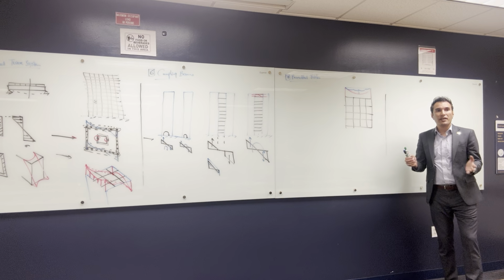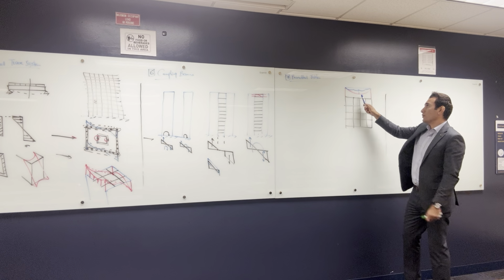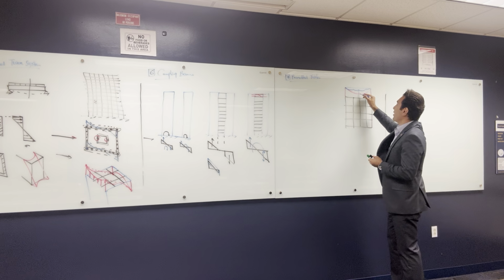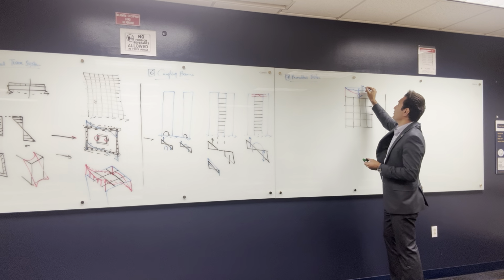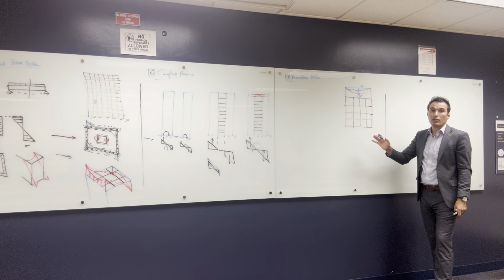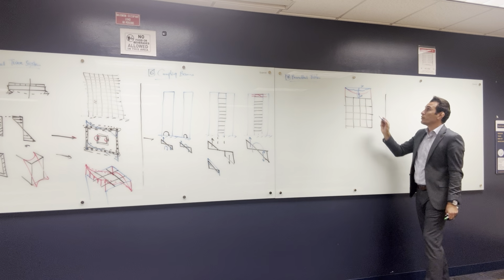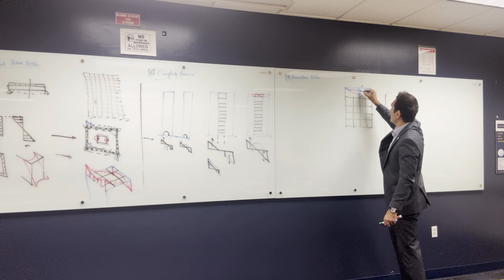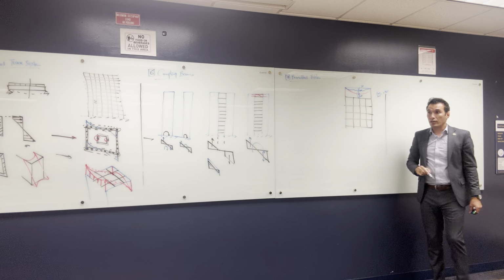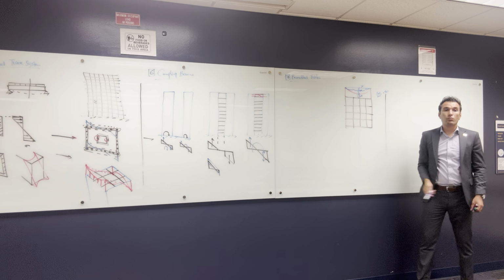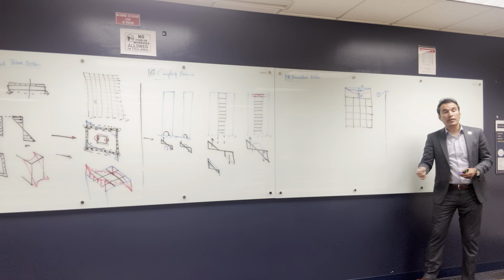So how can we determine the efficiency of the system? You come in the middle and you find out what the amount of shear lag is. Let's say you find that the force here is 100. But if this system acts perfectly, it should take, for example, 200 as a reaction. I mean the reaction of the column. So that means the shear lag is like 50% from here to here. It's like this is 100, so 100 over 200, so you have 50% shear lag, okay? So we measure in the middle and see how much shear lag we have. The less the shear lag, the better.